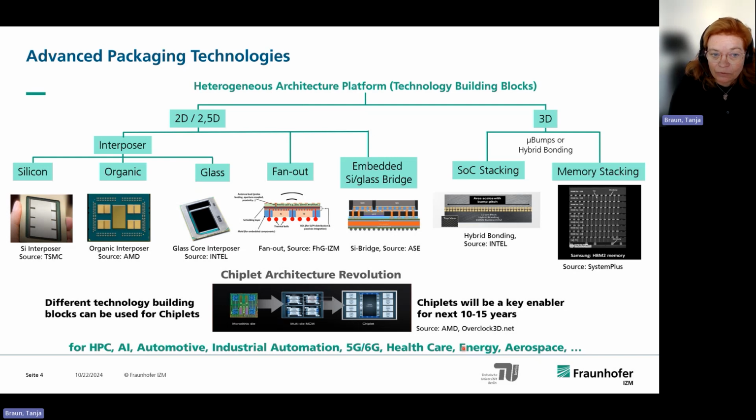And you see a little bit how the world is structured if you discuss about 2D and 2.5D architectures, of course, also 3D. And as Eric already showed, I think we will also cover some of the other topics here, especially on the organic interposers, on glass core substrates. I would now pick up that fan-out topic here. We'll give at least some comments on maybe bridge technologies, which maybe we will see more in future. But you see, we do have a lot of options as interposer for advanced packaging. Of course, we have also silicon here, and we have the real 3D integration.